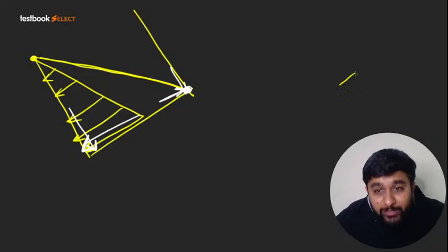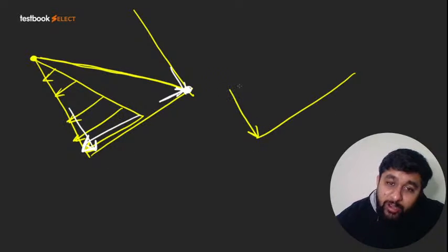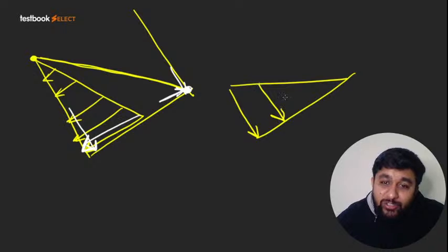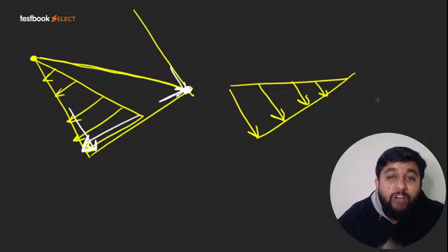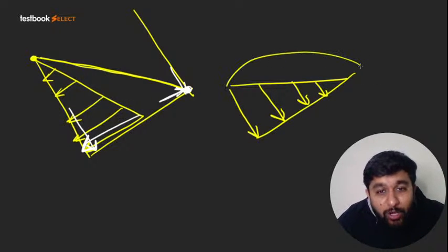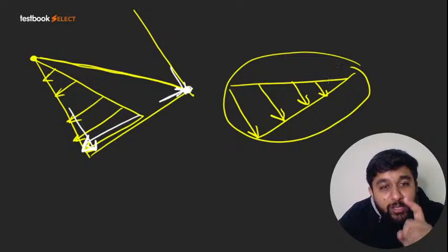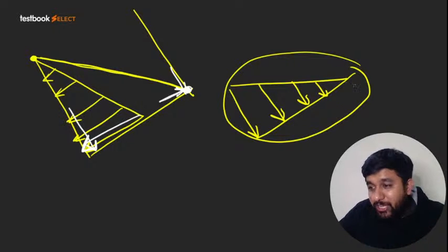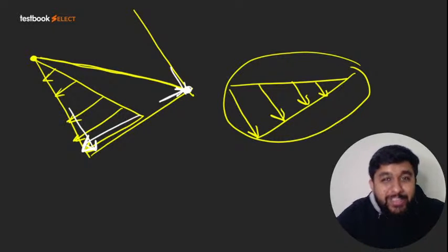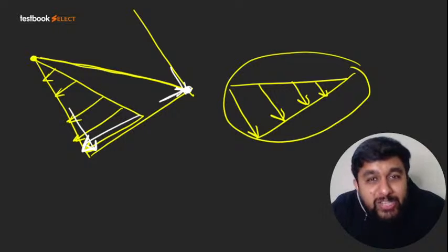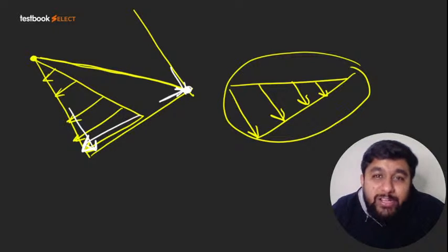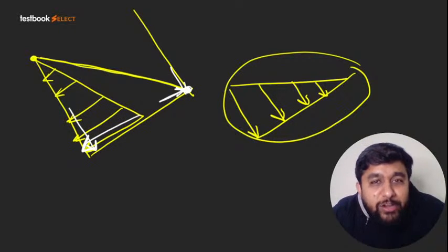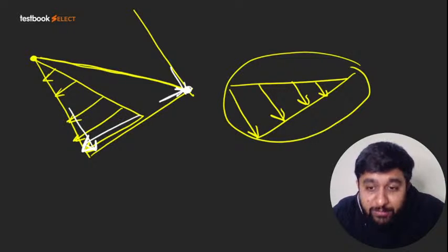So at the bottom surface the pressure distribution is like this. So we know the pressure distribution of the bottom also. So the volume of this pressure prism will give us the pressure force. Okay? So in this way you can find out the pressure force on all surfaces also. So it's the same concept which I use every time I teach this subject.